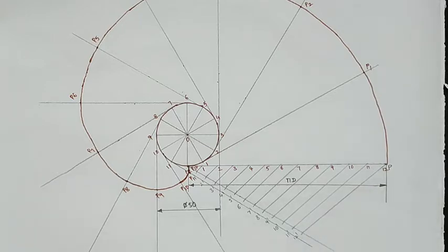By following the divide a line method, from point 12 we will draw an inclined line at any angle, and divide that inclined line into 12 parts, and joining 12 dash and P, through the points on the inclined line we will draw the parallel lines and locate different points 1, 2, 3, 4 up to 12 on the horizontal line.